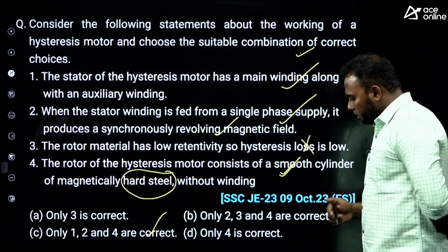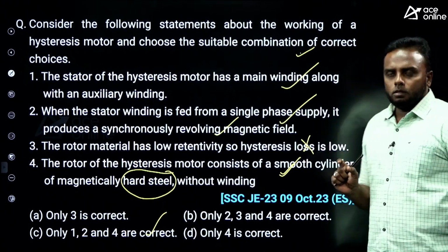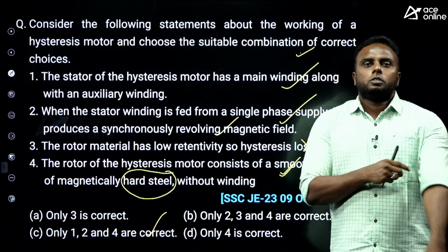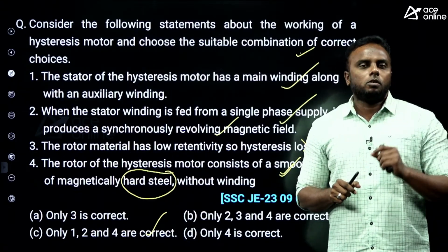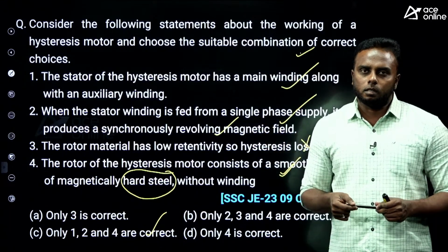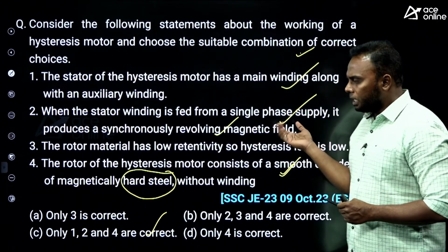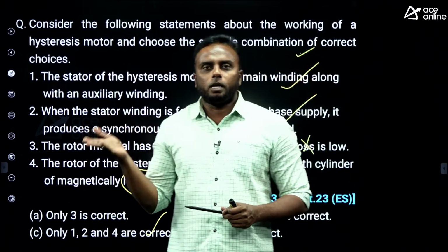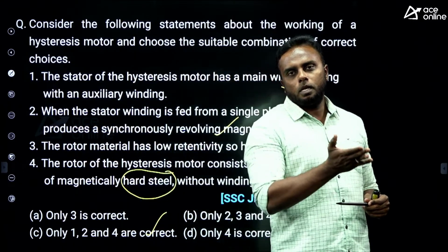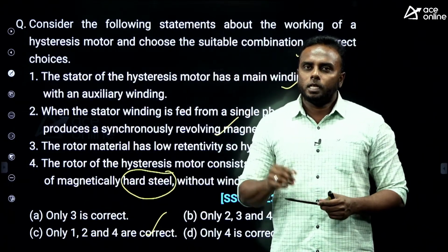So these are some questions from DC and synchronous machines. Those who are attending the coming SSC JE exam, try to go through mainly the synchronous motor: starting methods, why it is not self-starting, what the starting torque of a synchronous motor is, and how a synchronous motor on a bus bar behaves. When does it behave as a capacitor or condenser, and when as an inductor? An overexcited synchronous motor behaves as a capacitor.